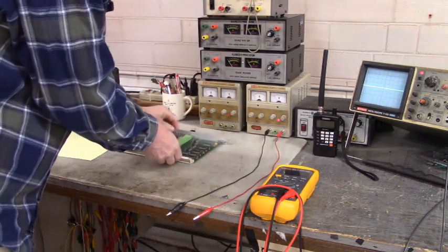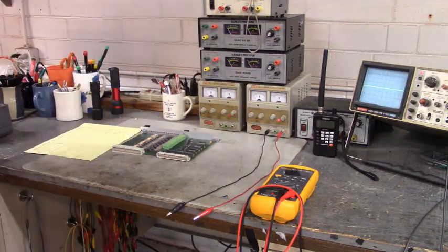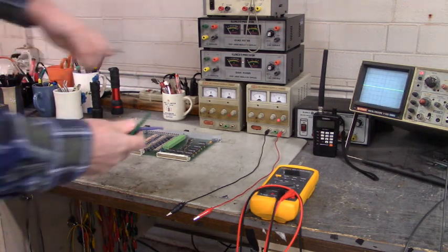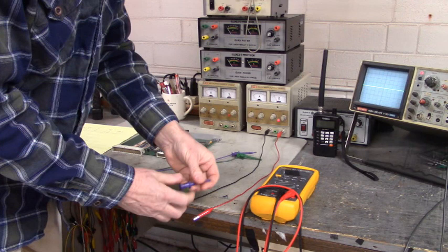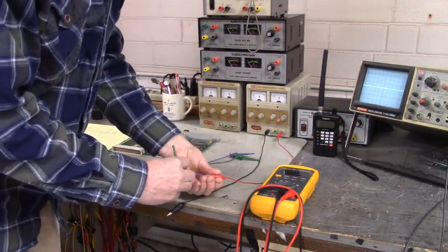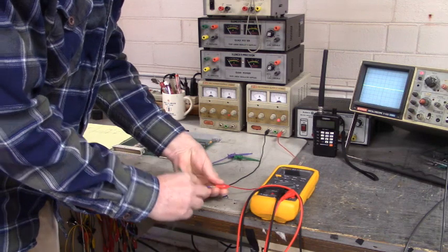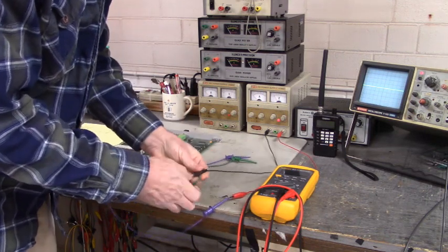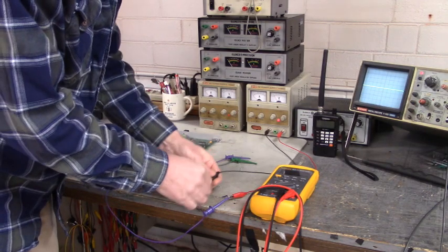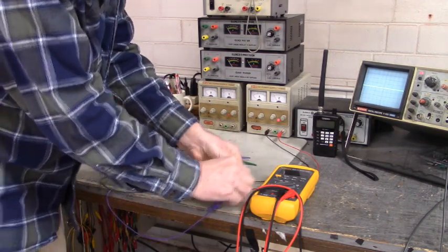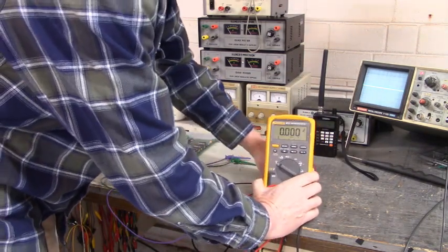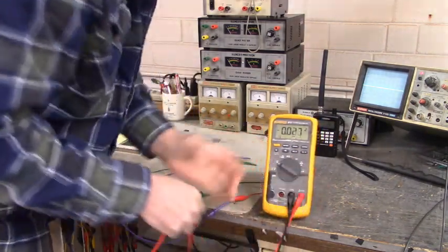This part right here gets a little bit tricky and you got to be careful. You have on the optocoupler input side 24 volts DC. And on the optocoupler output side, the NPN transistor output side of the optocoupler, driving into the logic of that Homag input card, you have plus 5 volts DC.